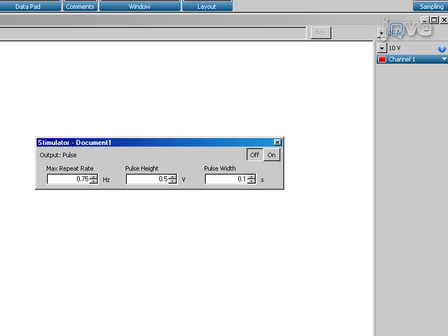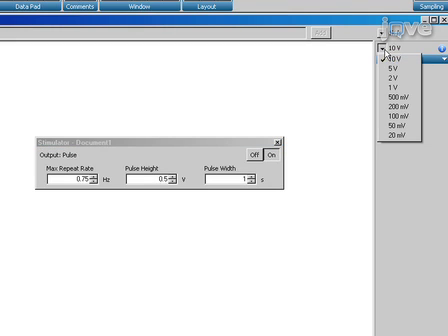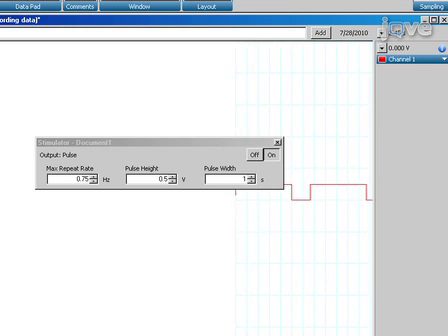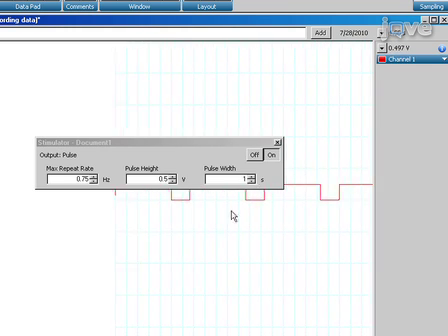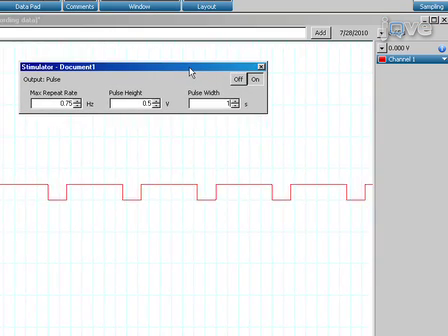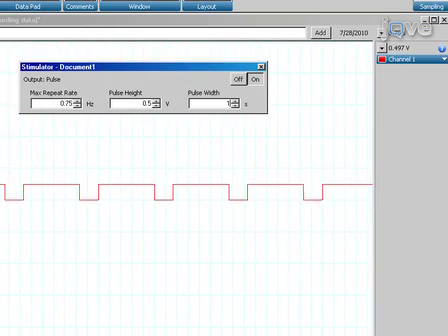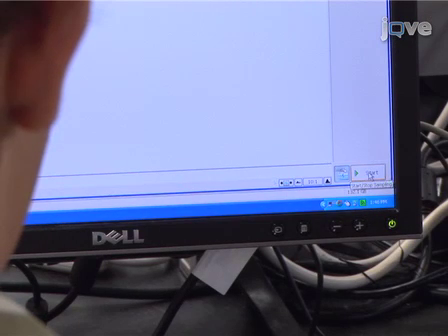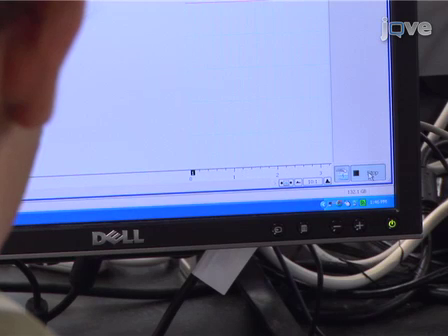The PowerLab will emit a voltage fluctuating between positive and negative 0.5 volts, which results in a peak-to-peak stimulus of 1 volt. Set the frequency to 0.75 Hz and the pulse duration to 1 second. For channel settings, select Channel 1 to monitor. Click on Input Amplifier and, in the box, click on the differential button and set the range to 5 volts and select OK. The next step is to apply an electrical signal to the nerve cell model and examine the loss of the signal along the length of the model.